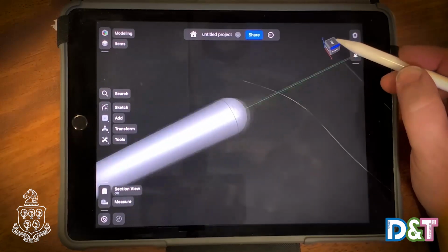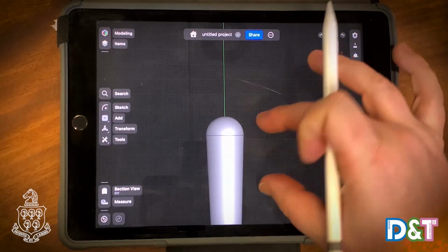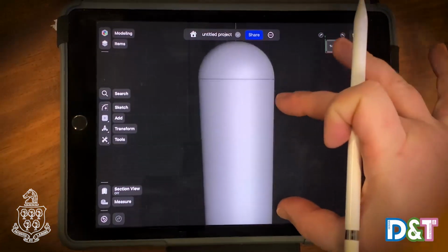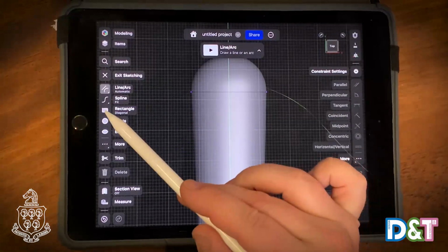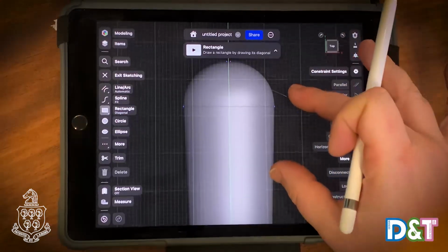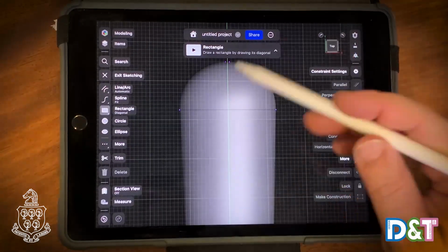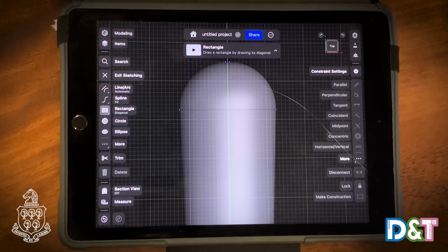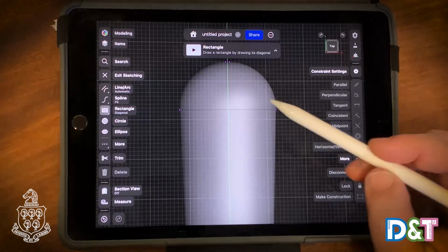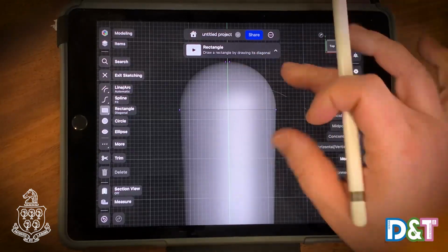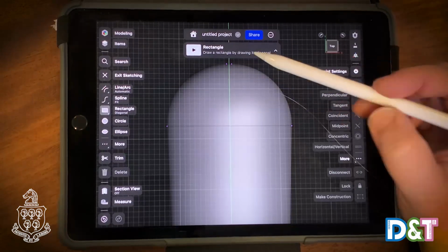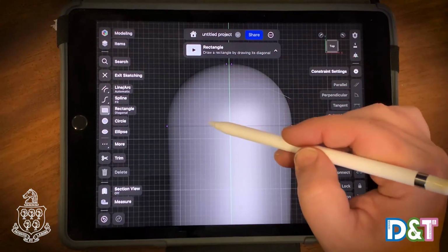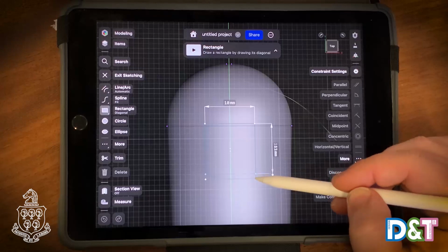So I normally select the top view, so you get a really nice straight top view. And we're going to go into our sketch settings. And at the moment, we're just going to draw a rectangle. So if you imagine the curved oval that's in your engineering drawing as a square, it's drawn out that it's 10 millimeters by 28 millimeters. And it's 12 millimeters from that end. So if you zoom in, you can see every single millimeter, and I know 12 is just here. So what I'm going to do is draw a quick little shape here.